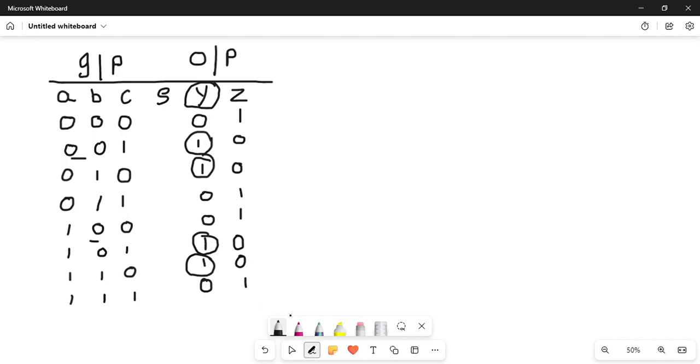I'm so sorry students, yeah, okay. This one, this and this one and this one, so these two and these two are getting evaluated to 1 in the case of sum. So if I write 0, 0, 1 in terms of this particular ABC, how can I write it as a min term? It is nothing but A bar, B bar, C, right?